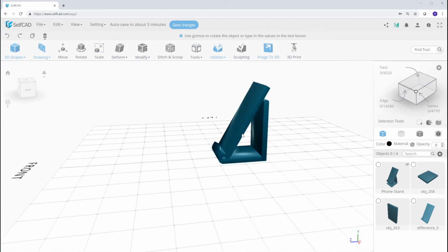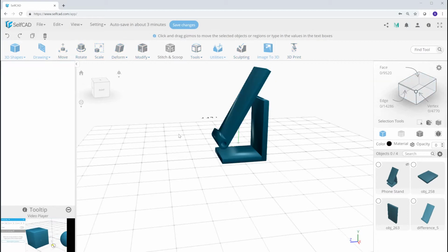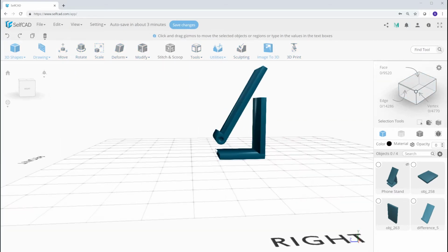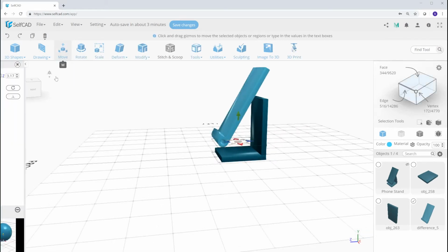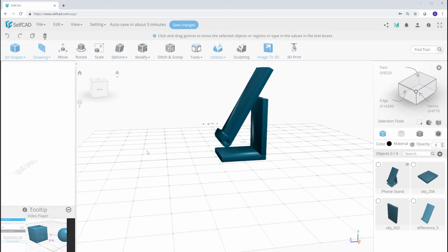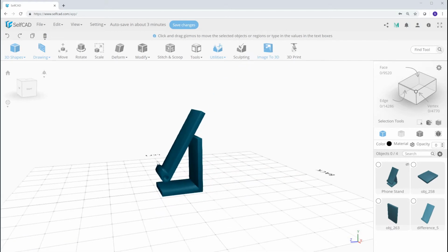Finally, the form is taking shape, but we're not done. To get clearance for the post-its, we will move the phone platform up 30 millimeters. This will work, but to make the front nicer, we will align the front edge of the base and the platform. This will be done by setting the position of the platform to -4 millimeters on the Z-axis. It's a small change, but I would say it makes a big difference.